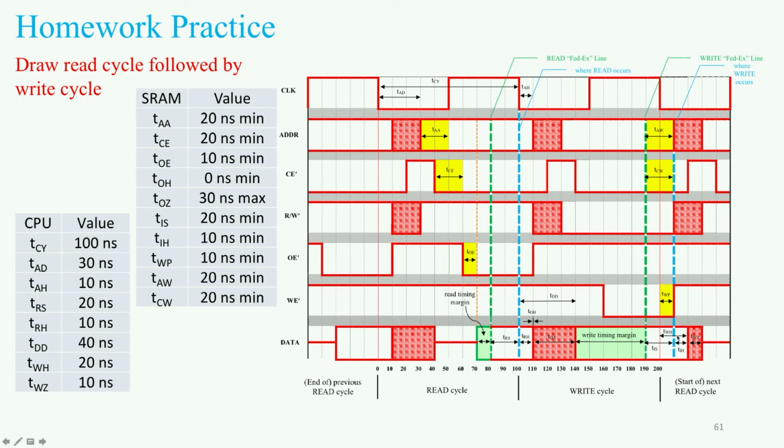The hold time effectively begins here because of the 10 nanoseconds of propagation delay, and then you've got to make sure that it's held for these 10 nanoseconds. And the 20 nanosecond write hold time inside the CPU guarantees that this is not violated.